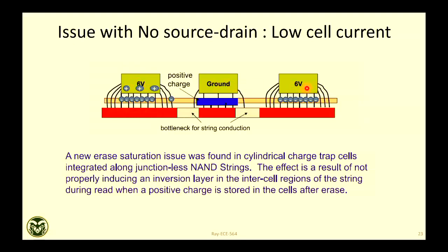Those green things are the word line. This red region is your polysilicon. So you can change the conductivity of this channel through the voltage on the word line. But what about this intermediate region? That's where you need to rely on the fringing field, and that will reduce the conductivity of the channel.